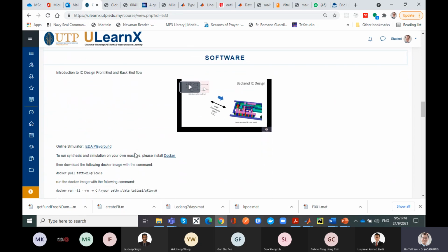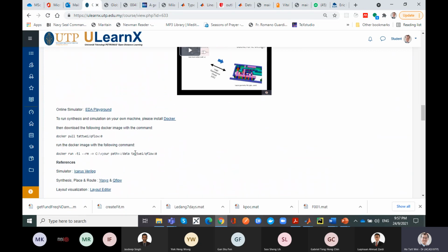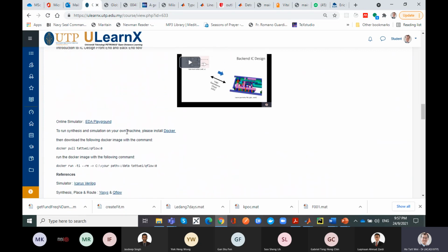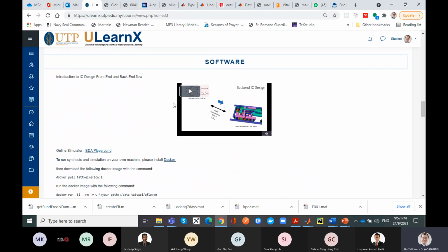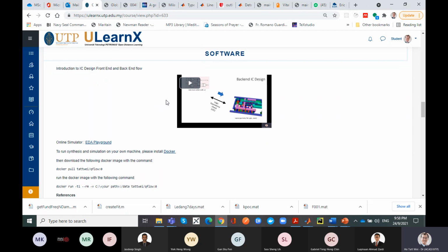So further on that, I'll mention the tools we are using. In this course, I'm using purely open source tools. I understand that maybe in your IC design environment, you will have Cadence or other tools like that. That's okay, you can use that. The key part is you just have syntax differences, but those tools are kind of expensive, and I've put together the flow. For this front end design, you would only need a Verilog synthesizer and a simulator.